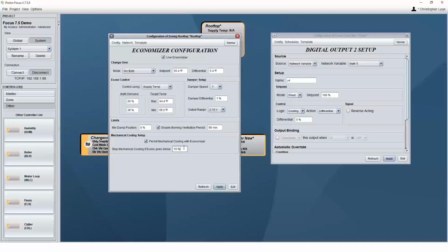We get that damper wide open, bring on a compressor. Well, now we're going to get below our target supply temp, so we'll start closing the damper down. So at this point, it's almost like our economizer has become that vernier stage, that trim stage that we've been talking about with the compressors and the digital scrolls, okay?